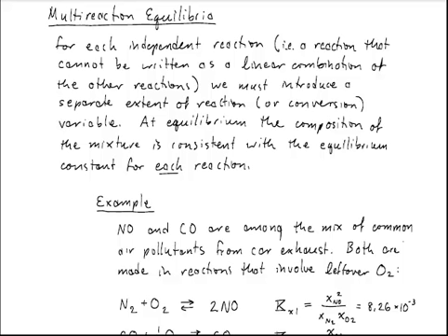The basic idea from a math perspective is that each reaction has an associated equilibrium constant, and that equilibrium constant serves as a constraint on the final equilibrium in the reactor. Each species involved in those reactions is a degree of freedom. As long as you're writing things down correctly, there will always be at least as many species as reactions.